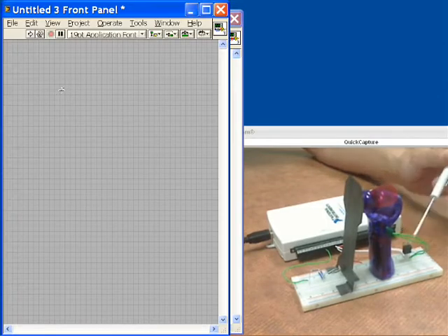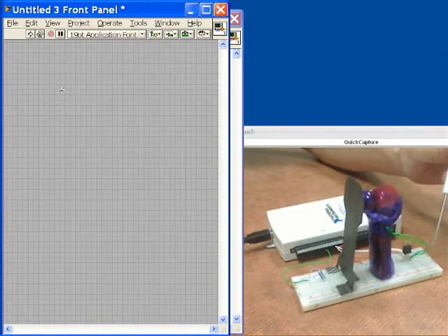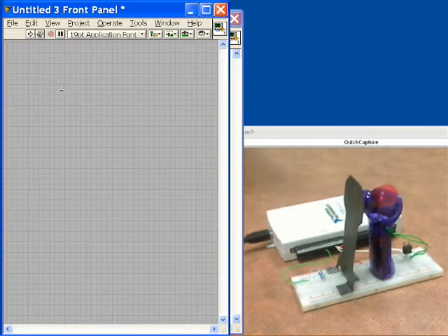So we take the analog output coming into the base of the power transistor, and then in the emitter and the collector we're just using that to control the amount of power in the fan itself. So as we change the analog output voltage, the power of the fan will change.